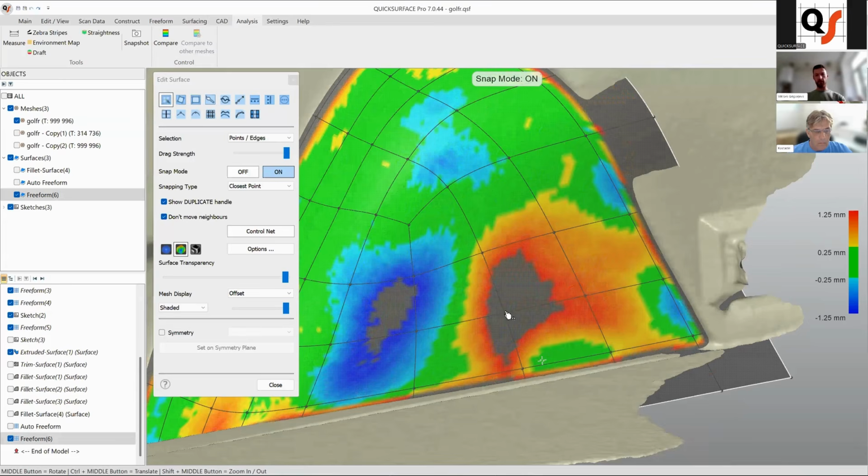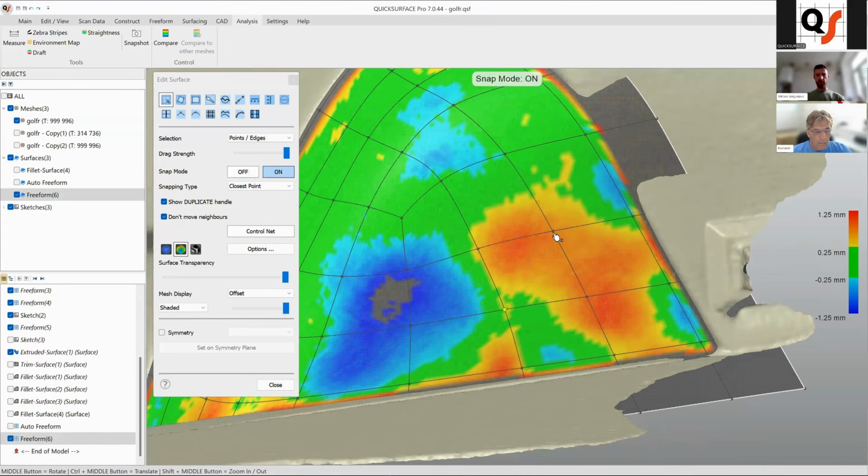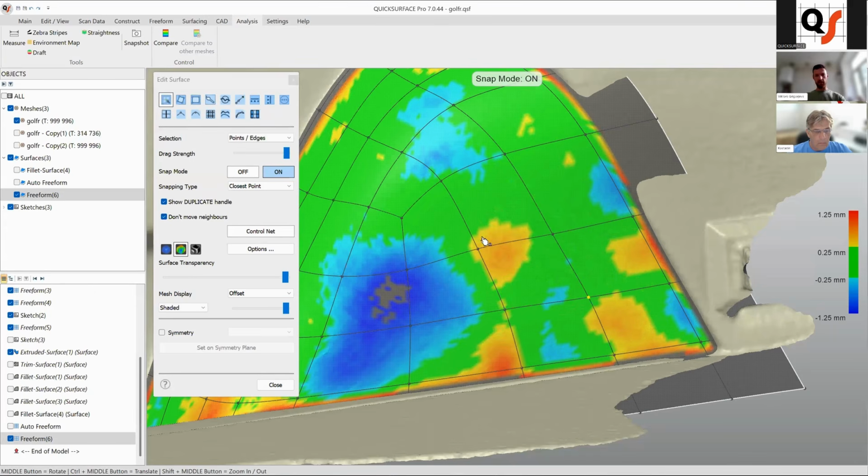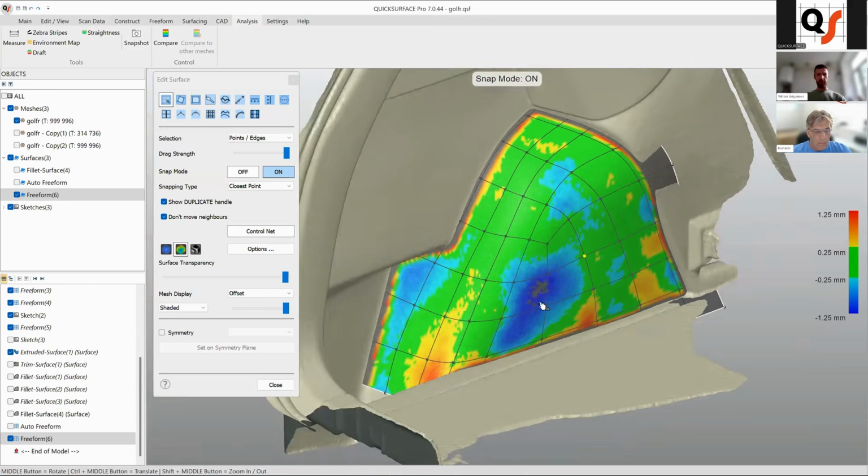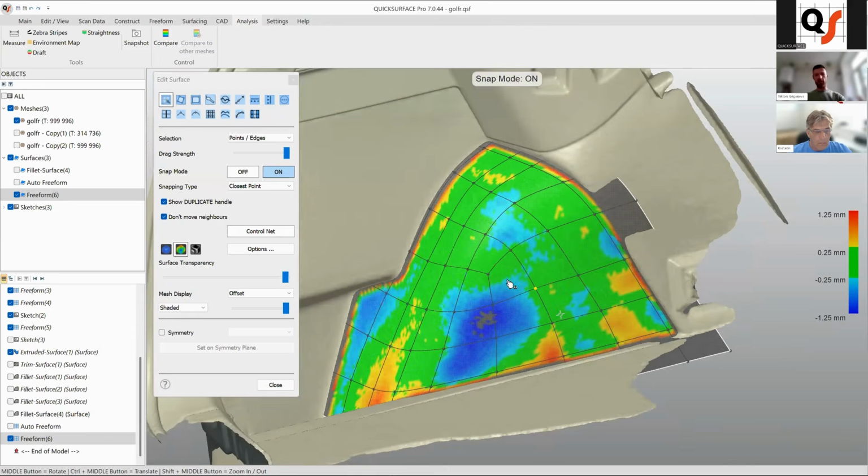So you need more deviation tolerance, or you want more smoothness of your surface. This is always the question for you as a reverse engineer. How do you want to proceed with your reverse engineering tasks? So you have to consider some facts always. Same as diameter dimensions, you have to round it up to some point, or as in this case, you want to align to deviation, or you want to make smooth panel.